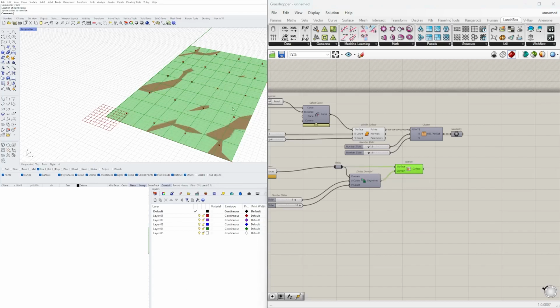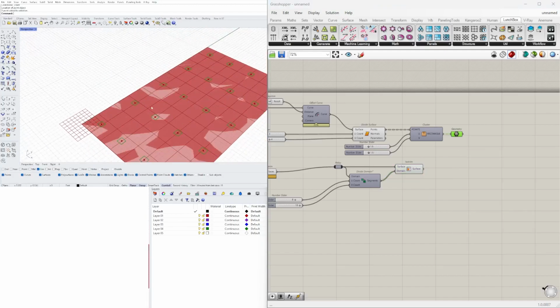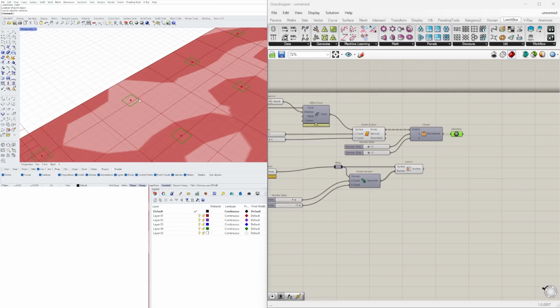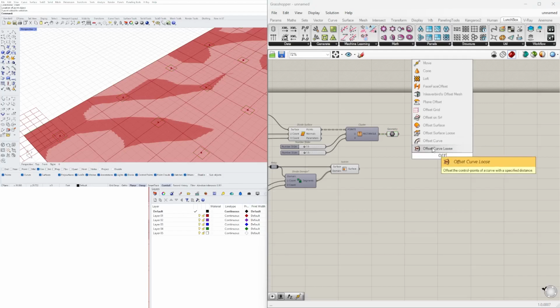So now that we have this surface, now we can create the waffle. Actually, no, we need to create the pattern here. So let's go here to this one. Now with this, we will actually offset to the outside because we don't want the waffle slab to go right up to the columns. We actually want it a little bit to the outside.